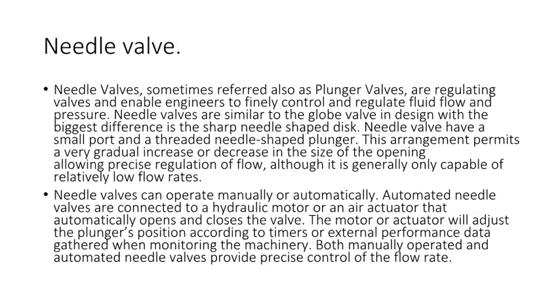Needle valves, sometimes referred to as plunger valves, are regulating valves and enable engineers to finely control and regulate fluid flow and pressure. Needle valves are similar to the globe valve in design, with the biggest difference being the sharp needle-shaped disc. Needle valves have a small port and a threaded needle-shaped plunger. This arrangement permits a very gradual increase or decrease in the size of the opening, allowing precise regulation of flow, although it is generally only capable of relatively low flow rates. Needle valves can operate manually or automatically.